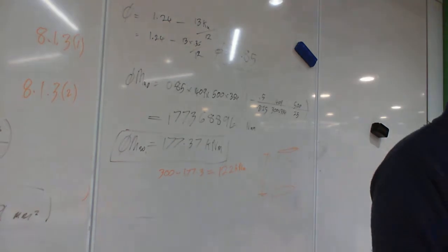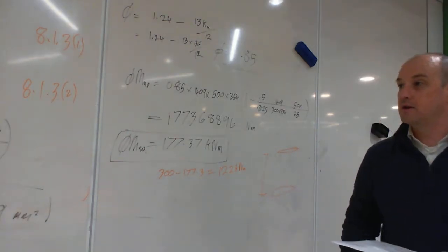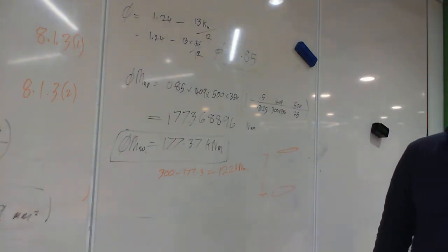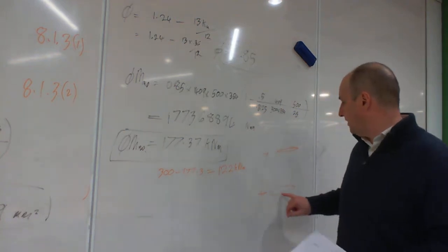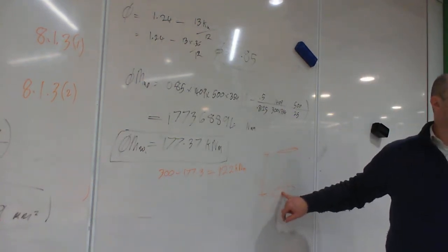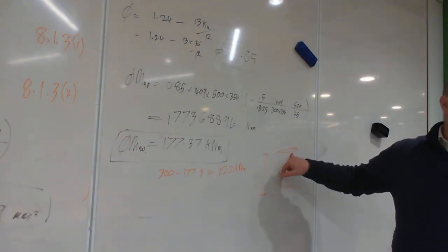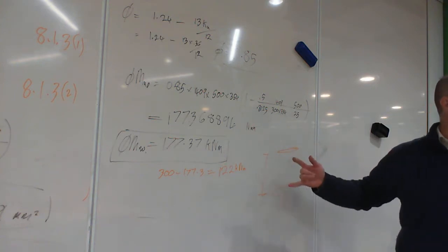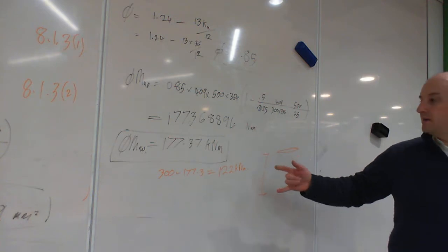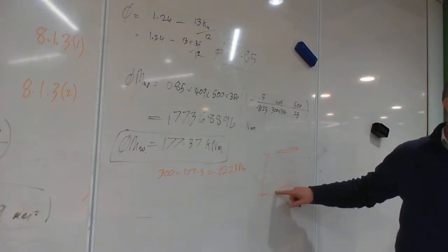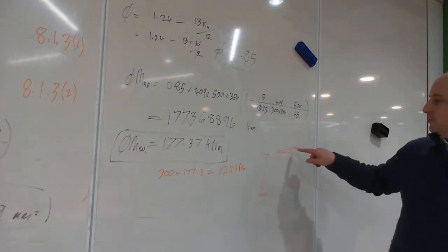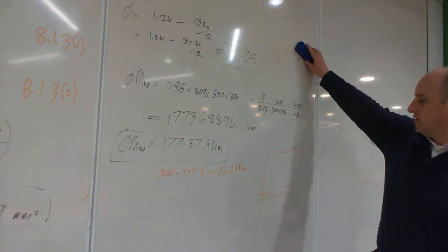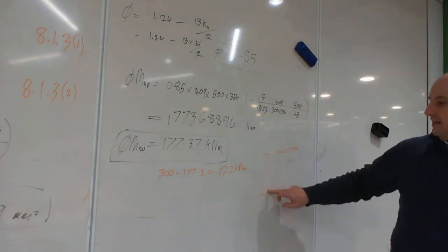All right. So what we'll do first is work out what the bottom steel is, and then there are a few factors we have to apply to work out what the top steel is. If they were both fully yielded and isolated, they would be exactly the same amounts of area. But there are a few factors which mean this one has to be larger. So, first thing is that lever arm.